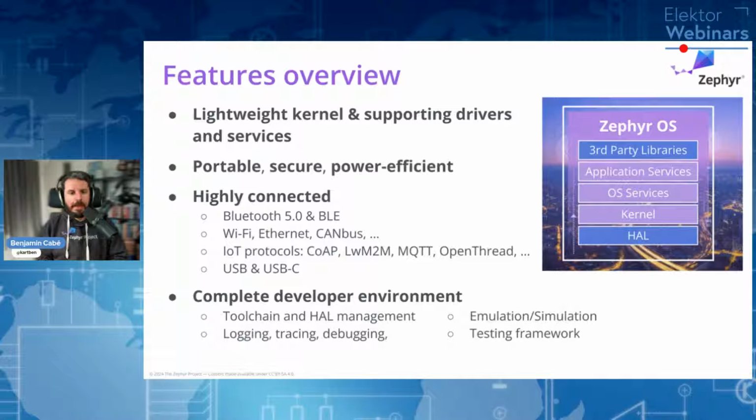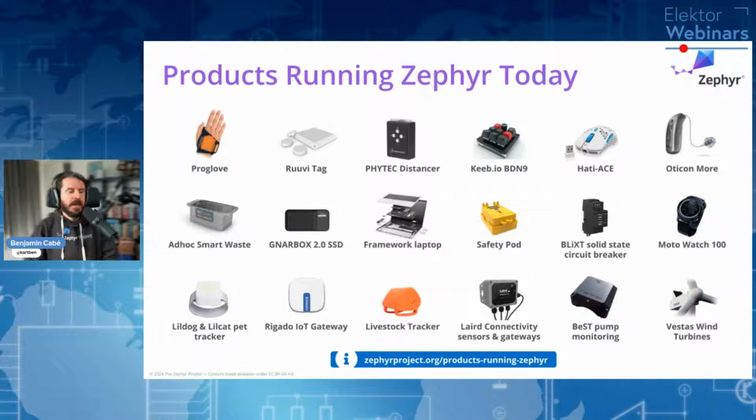All the HALs are going to be sourced automatically. You're going to have tools to help you with compiling your code, with debugging, running unit tests, and running reports to get a sense of how much memory your application is using, etc. So yeah, that's Zephyr.